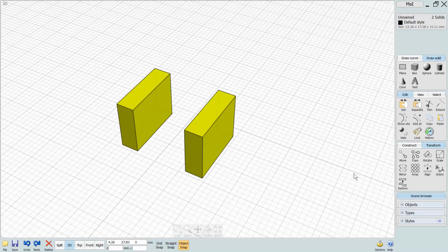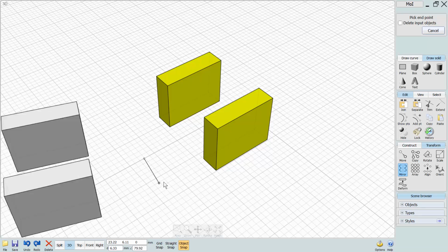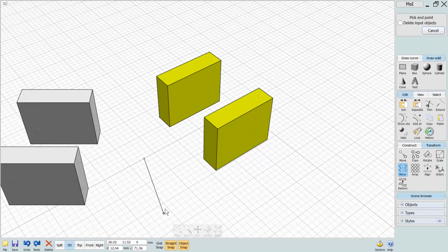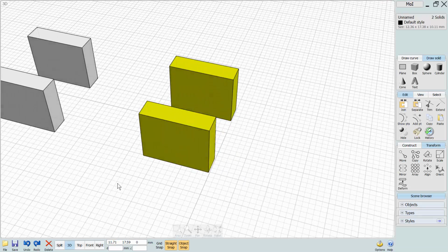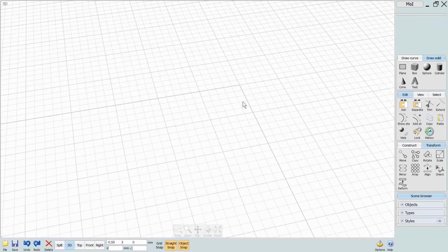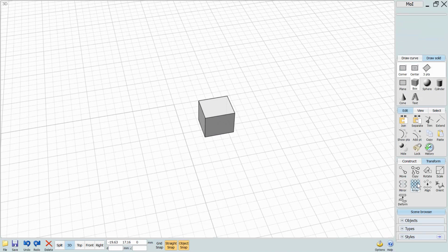So you need to select your items, click on mirror, and then pick a start point, scale like this, rotate like this. Let's use straight snap. I want to snap the second point to this guideline, and then click, and Moi will create those 2 copies. Super simple. Next option is this array.